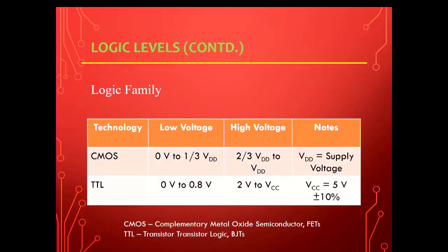I'm talking about like 10 nanowatt, whereas TTL would consume about 10 milliwatt. So that's a huge difference. So in small electronics like cell phones and tablets and other electronic gadgets, you'll see FETs being used, and they're actually working on increasing density, meaning more gates in a small piece of area.